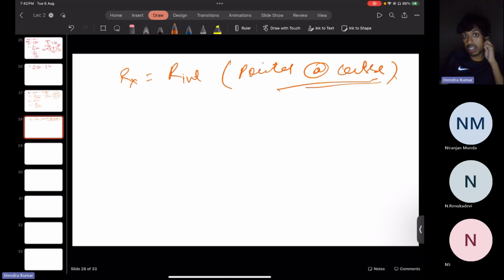So for that, what generally we do, because every time we cannot keep changing? Let's say we have purchased one ohm meter of internal resistance of 1 kilo, and we have a requirement to measure the resistance of 30 kilo. So we will not go again and buy a different ohm meter, right? Because that will be a violation of the purpose. So what can be done? You can change, you can tune the internal resistance. How? By connecting one more resistance to the circuit.